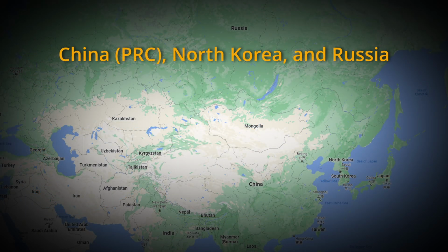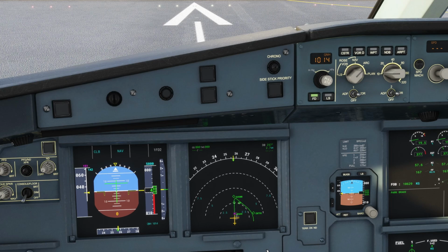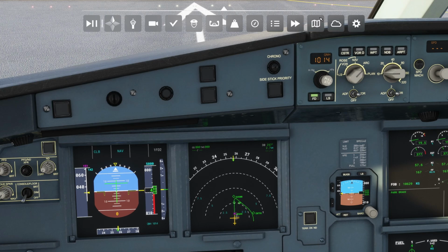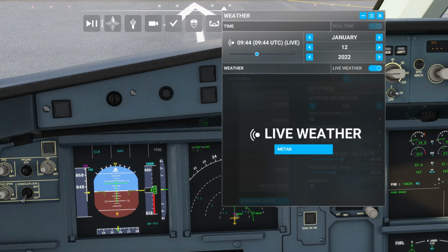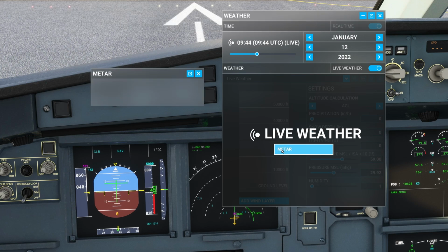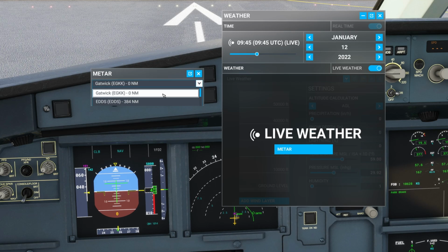Whilst not applicable to what we're doing today, there are a number of countries that don't measure altitude in feet, but in meters, such as China and Russia and so on, but we won't be looking at that in any detail today. Being at Gatwick, in the south of England, the transition level is 6,000 feet, so I can't use the standard pressure setting. I need to get my local QNH or pressure setting.